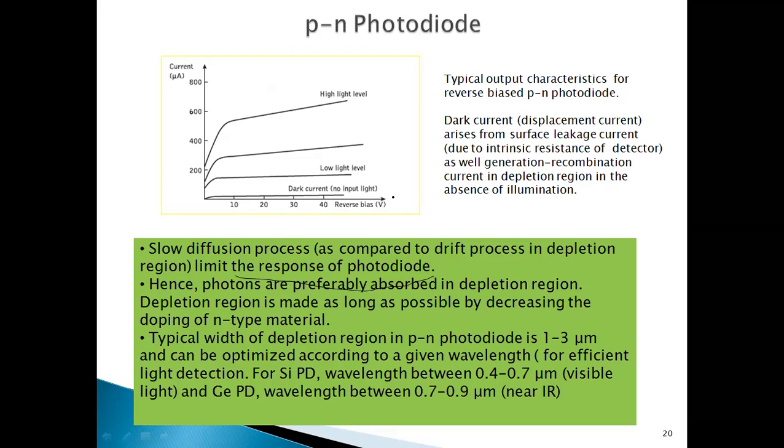I've mentioned this in part 2 of lecture 9: we have the minority carriers in your PN material, and the movement of these minority carriers without the excitation of photons will also produce a current in your external circuit. This current, produced by the flowing of minority carriers, is called a dark current, and it happens without any photon excitation of this semiconductor photodiode.